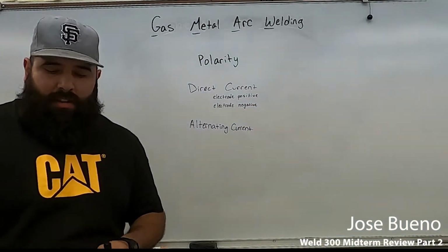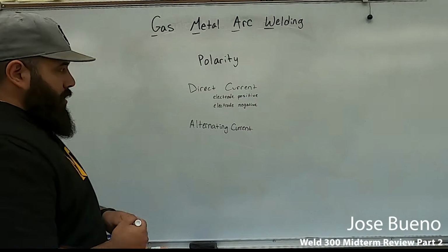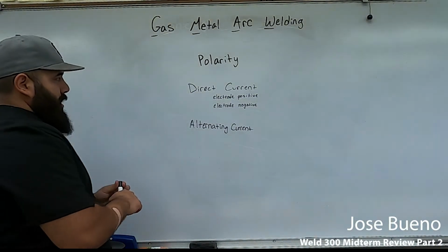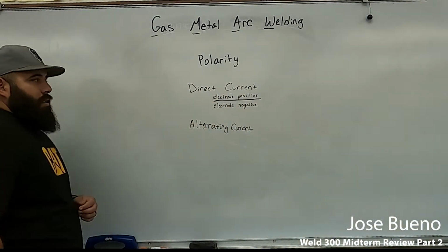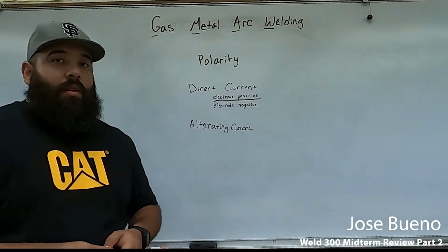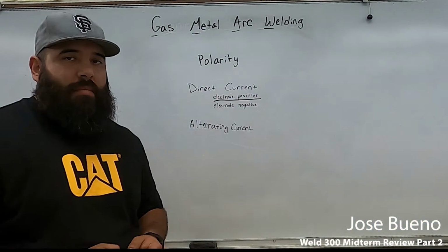Using GMAW in our course, we are actually using direct current electrode positive. So the same polarity that we were using with SMAW.